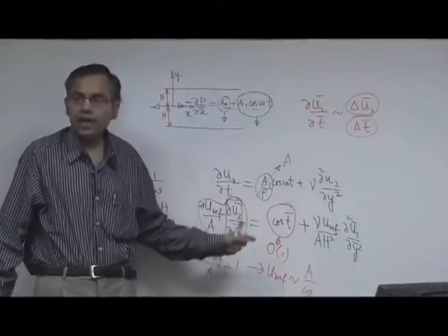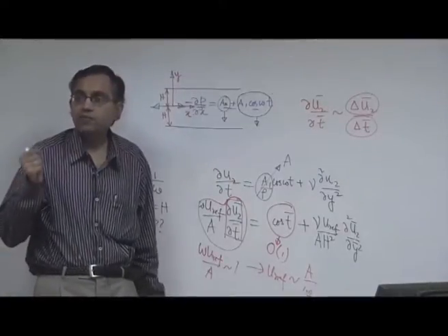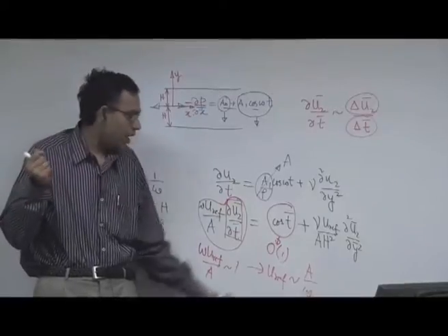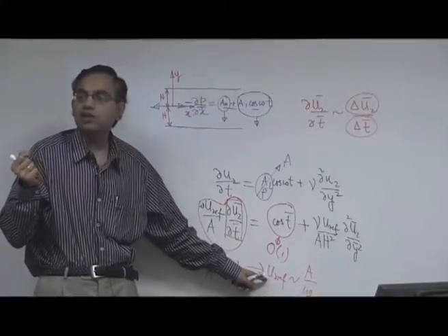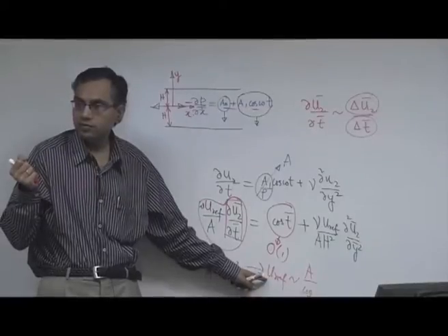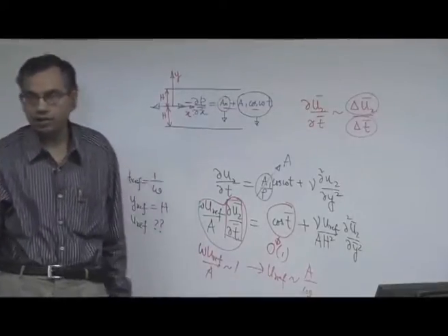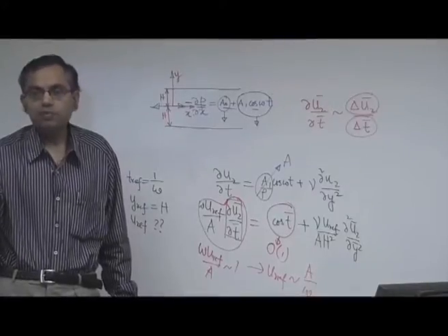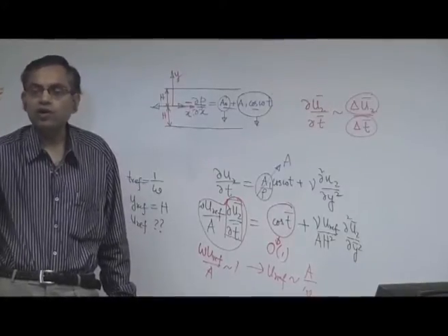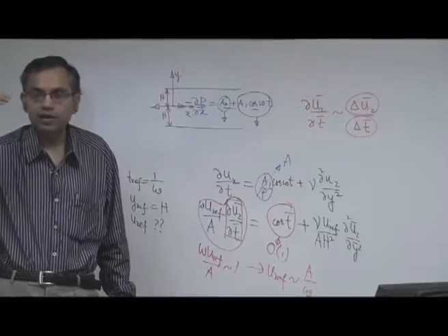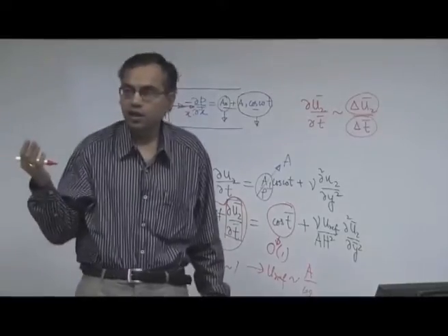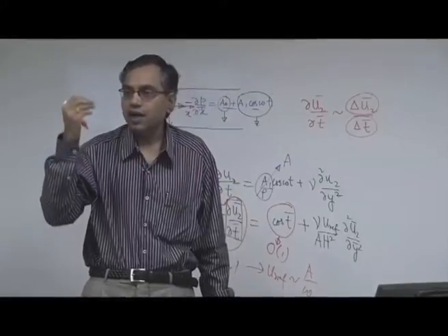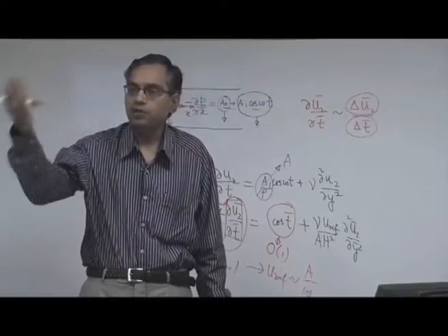So, this gives us a nice physics that if you have a driving pressure gradient which has an oscillatory component, how can you get the corresponding velocity scale? Even for engineering this is important, because say you may have a pump that pumps the flow in an oscillatory manner. Now, as an engineer you may be interested that, well, this is the oscillatory pumping power.